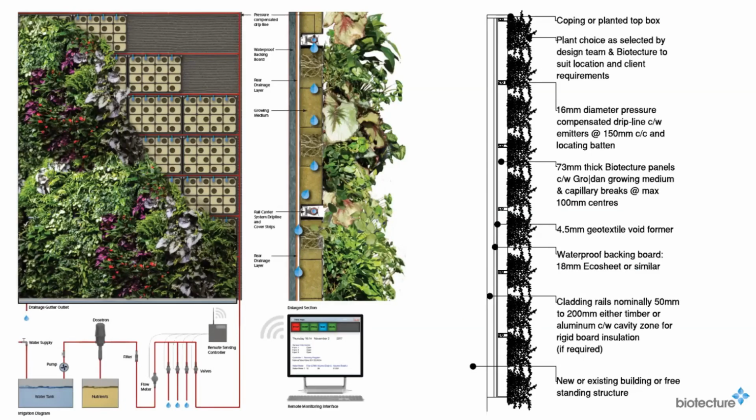And whilst on that subject, it is very precise, low volumes of water that we're using. These are quite sophisticated systems, both from an irrigation system point of view and a monitoring point of view. So we're watering precisely at the root zone, reducing any evapotranspiration losses from what we're watering with. So we understand that we're watering much lower than general grounds maintenance in terms of per square meter watering. And the electricity costs for the pump are also very low. So the benefits that come from installing well-designed green walls far outweigh the inputs in terms of water and electricity.